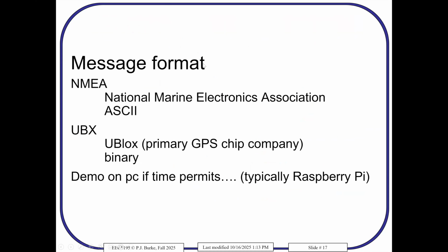A little bit about the message format. It's sending two possible formats. It's a bit stream. One of them is an ASCII bit stream, so you convert it to ASCII text and it's human readable. The other is a binary bit stream, which has to be converted if you know the format, and the format is public, but it's binary. So you have to parse the binary.